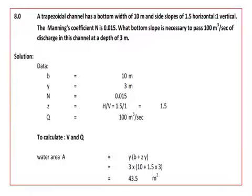So in this problem we are calculating for a trapezoidal channel where the bottom width is given. The bottom width B is 10 meters, and the side slope is 1.5 horizontal to 1 vertical, so it is H by V, which is 1.5 divided by 1, so therefore Z is 1.5. Discharge is given, which is 100 meter cube per second.